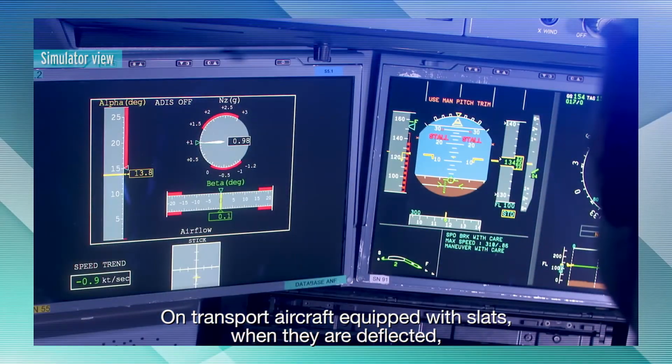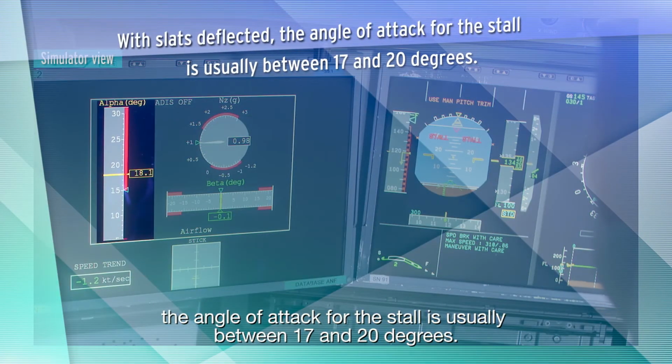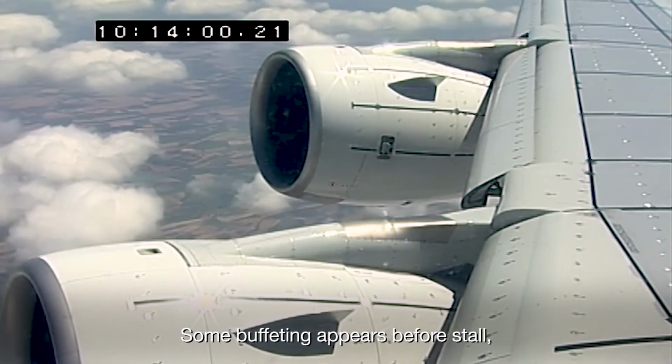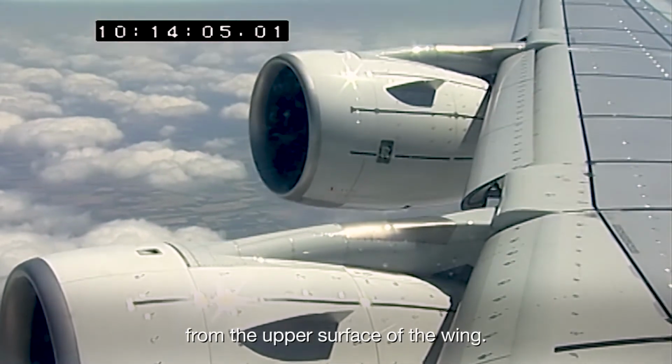On transport aircraft equipped with slats, when they are deflected, the angle of attack for the stall is usually between 17 and 20 degrees. Some buffeting appears before stall, linked to the separation of the airflow from the upper surface of the wing.